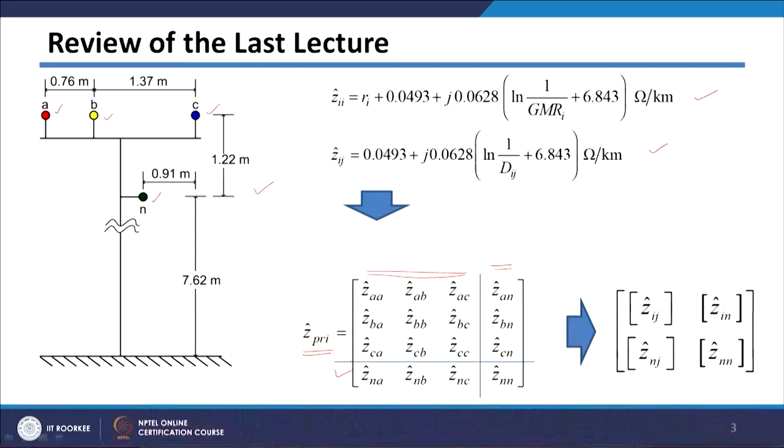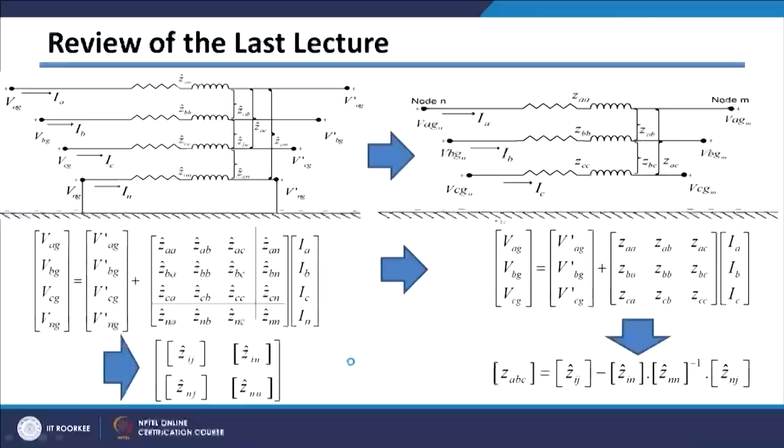And in your calculations like load flow calculations or short circuit calculations, we do not want to take these neutral conductors into account. So, we want to eliminate them, and for eliminating these ground conductors, we have seen that we can use what is called Kron reduction. In Kron reduction, first we have to separate out terms which are related to phase quantities or phase conductors.